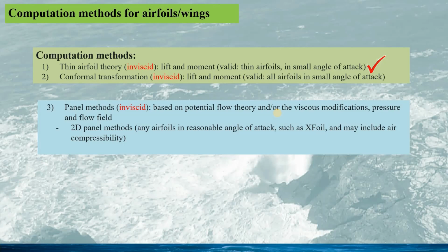We have the 2D panel method for any airfoils at reasonable angles of attack, such as Xfoil, the open source panel method. This panel method might include the air compressibility. The 3D panel method can be used for the whole aeroplane with lifting and non-lifting bodies, and the air compressibility can be included in the analysis.